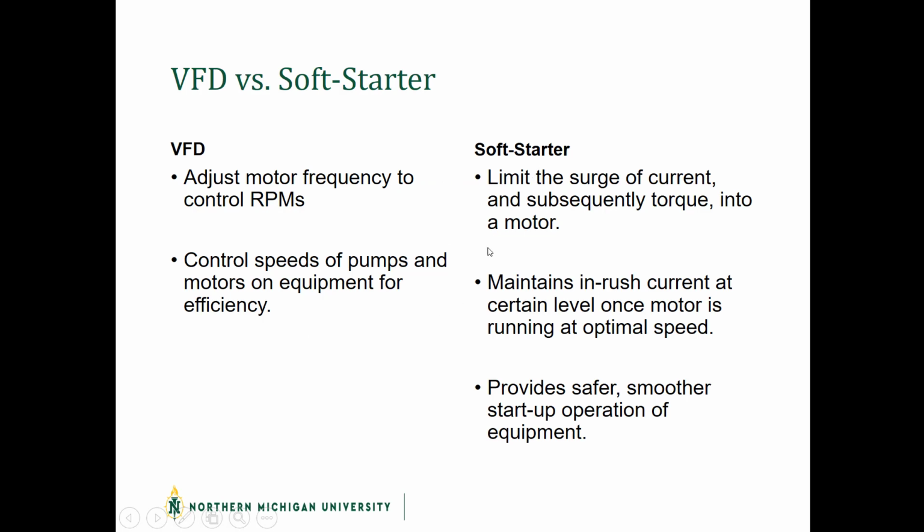Another piece of equipment is a soft starter. A VFD is obviously controlling how things go once we are in operation. A soft starter limits the surge of current and the subsequent torque to the motor. Again, if something's turning on, it's saying I need X amount of power because that's how it's designed to run. It's going to be pulling all that load right off the bat. A soft starter maintains that current at a certain level until the motor is running at optimal speed. It provides a safer and smoother startup of operation. Again, it extends the longevity of that equipment, so we're not just throwing electrical power at it right off the get-go. We're easing into it. So that's what a soft starter does.